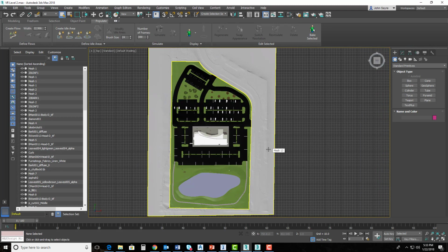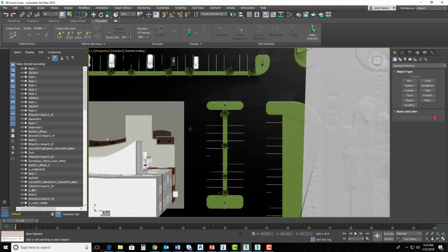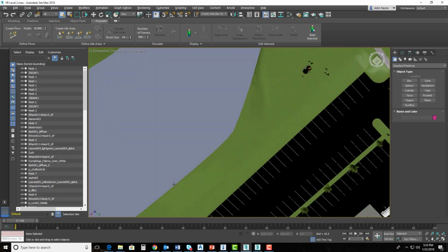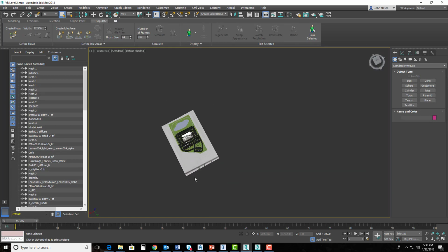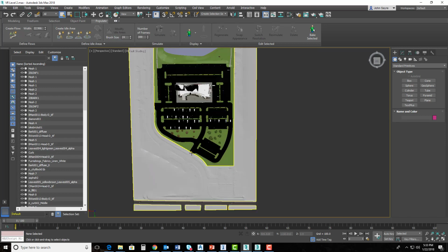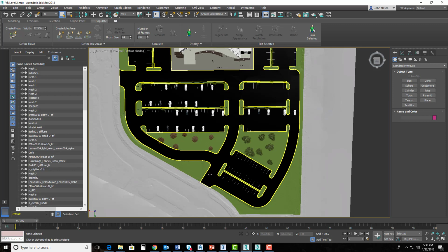Now, in our 3ds Max model, I want to actually draw this thing from the other end. I want to flip this 180 degrees. Best way to do this is to change to our perspective view, hold our Alt key down and our wheel on our mouse and kind of spin it around. And I can zoom back and spin it around a little bit more. And then zoom back in because I want to place my line that I'm going to use for the car to follow. I'm going to place it from this direction. So once I do that, these next 2 steps are very important.